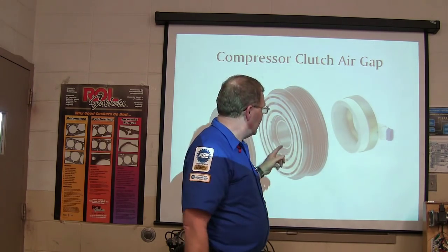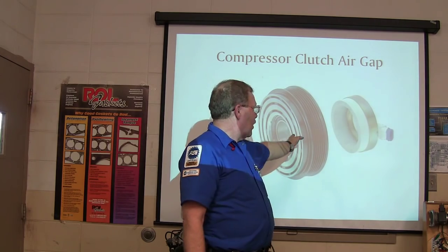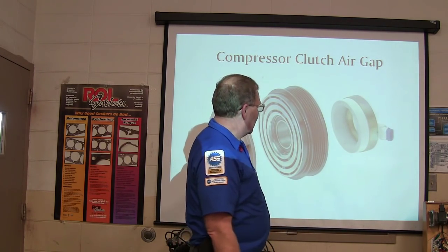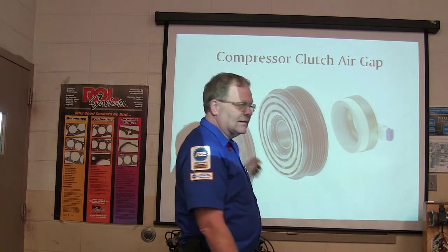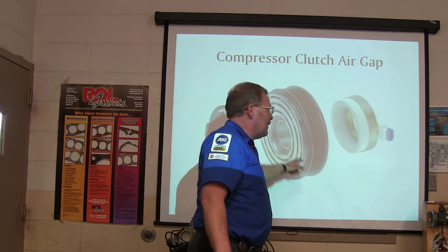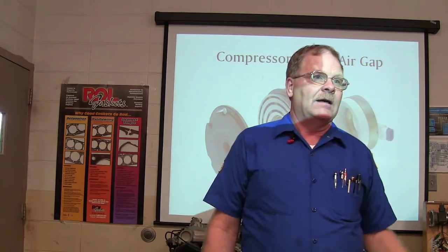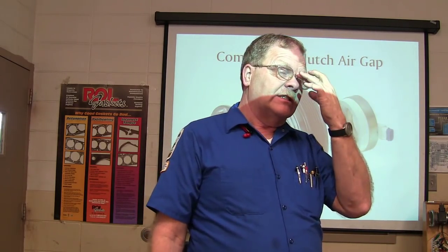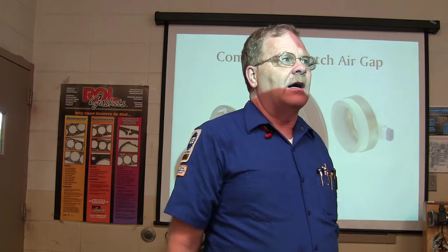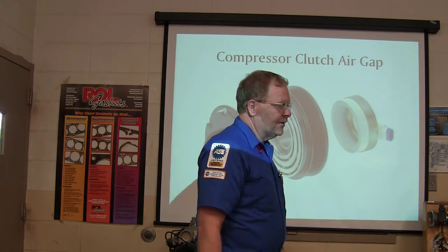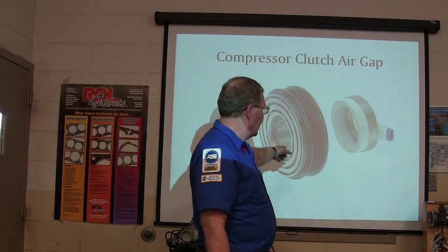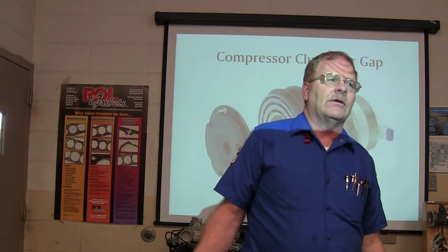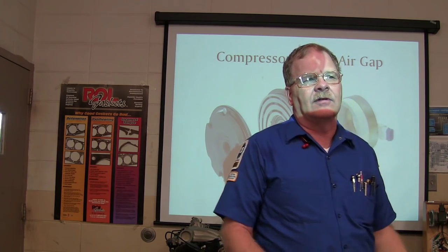But here's another thing. You cannot change this or that. You've got to change them together. And typically, even if you're able to buy one, you'll get that, this, and this. Occasionally, you'll see this bearing go bad, and that bearing will make noise, or it can lock up. I have seen situations where somebody thought they had a locked up engine, but when you take the belt off, the engine would start up because that bearing right there was locked up. This is a big pulley. Why do you put a big pulley on an accessory driven component, on a belt driven component?